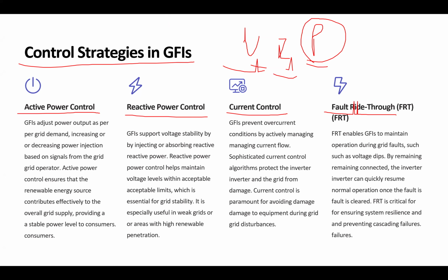But we all know that in a power system, because of the AC analysis, we have two types of power. Power here is not a scalar, it is a vector, a complex number. In any alternating system, not only three phase, power is defined as complex power, which is the vector that contains the active power and reactive power.